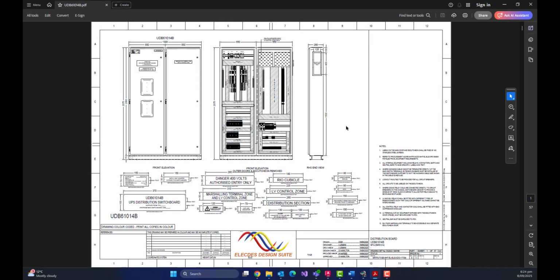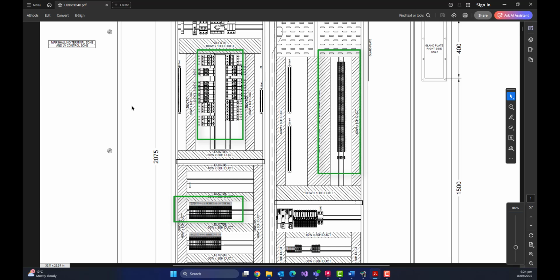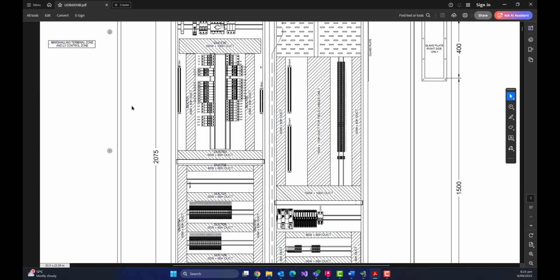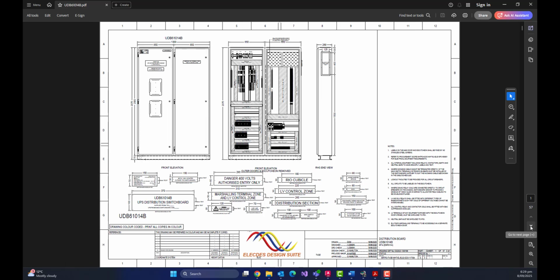The panel GA includes breakers, relay contacts, and terminals, all counted automatically by Instrument Manager based on the source file input. Now imagine generating the same type of panel but with a different number of components. Using the same import map files and templates, you can create an unlimited number of drawing packs for your project, even if the component counts differ significantly.